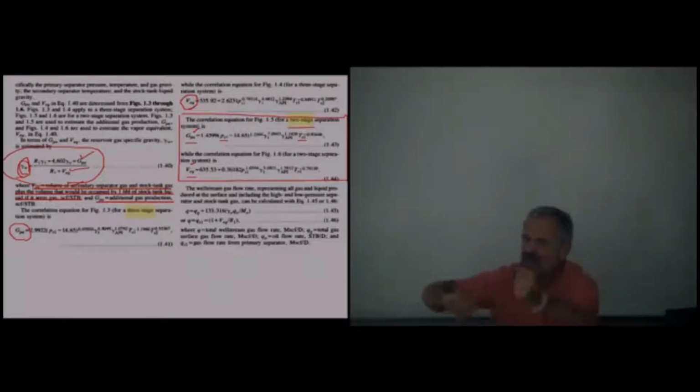which bring down the foam or the interface. See, I can speed up the volume of fluid that goes through my separator if I can reduce the layer of foam between my oil and water. Sometimes I do that with electrical current. Sometimes I do that with a chemical additive. But if I can do either of those and increase the output, I'm increasing the benefit of the operation.